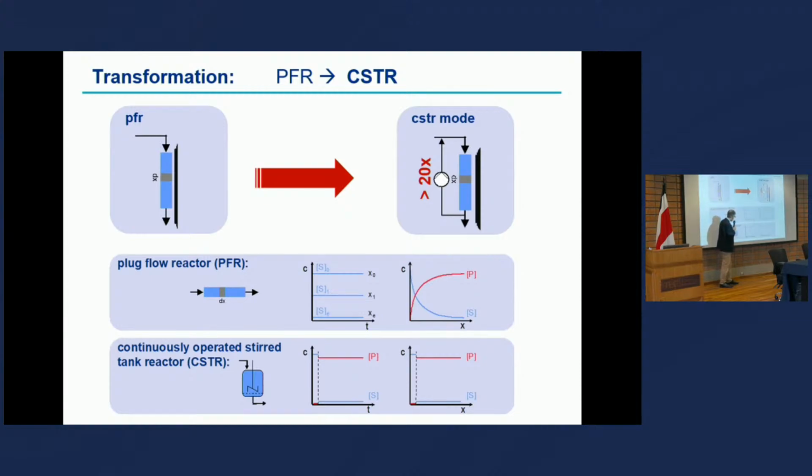And now if we add this minute, the next minute, the third minute, the fourth minute, the starting material, at a high concentration level, we will directly transfer to the product. This small amount we add here. And therefore we're dropping directly down to a very low, constant level of the starting material, and maintain a very high product concentration level, in contrast to plug flow, where over the length of the reactor in this 1 hour, we're maintaining longer time at higher concentrations of the starting material. Understandable?